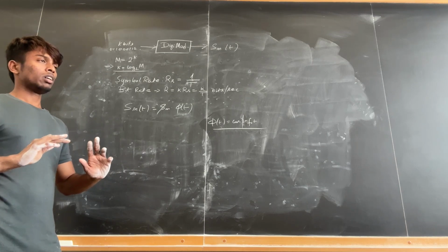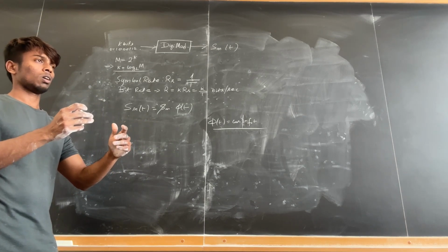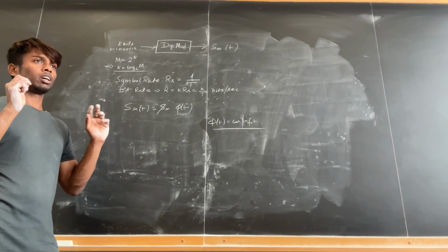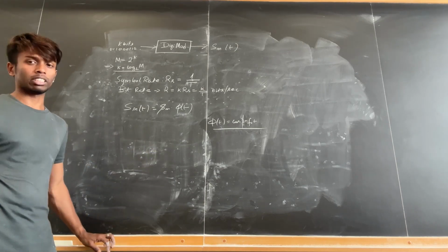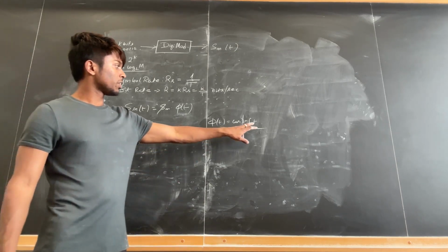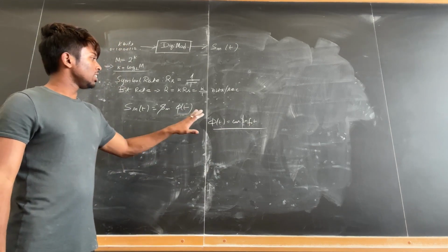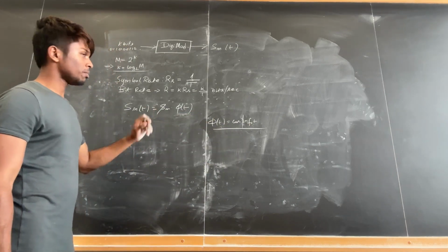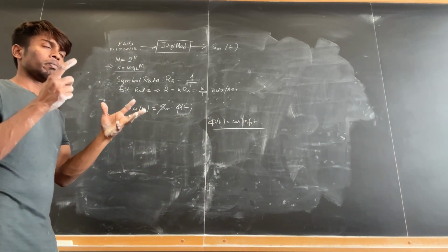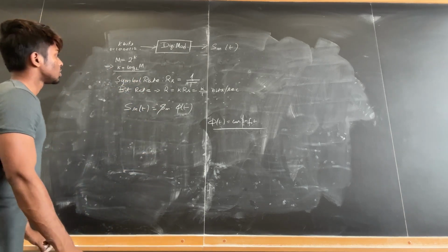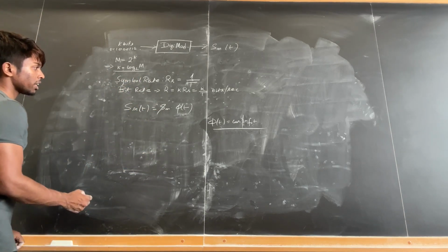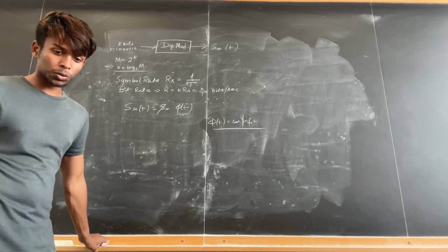So when we are transmitting data in any medium, we are putting the data on a carrier. So the carrier basically carries the data in the transmission medium, and this is the carrier frequency f naught. So phi(t) is that carrier, and s_m is some value. Now this s_m has a value space. So for k bits, this s_m can take a certain amount of values.